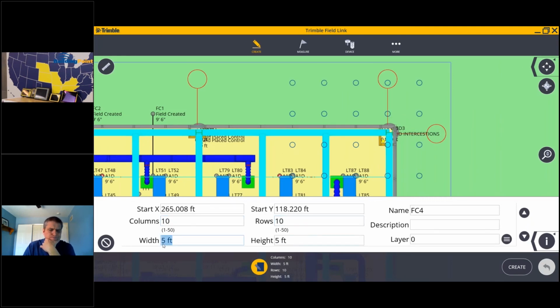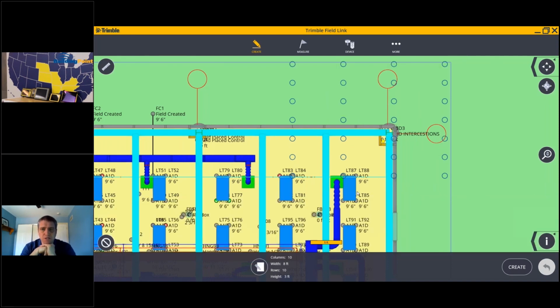Okay, where would you need this? I've used this a ton before when I wasn't done with my federated model in mechanical rooms or electrical rooms, and I wanted to grid the room on an 8-foot by 8-foot pattern that would allow me to put embeds, unistrut in the deck or whatever, so that I could still continue with my modeling, still continue with everything, but the grid would still allow me to use something in the field where I didn't lose my opportunity to get hangers or embeds in. Okay, so be sure you add the grids here and there as necessary when you're in the right scenarios.